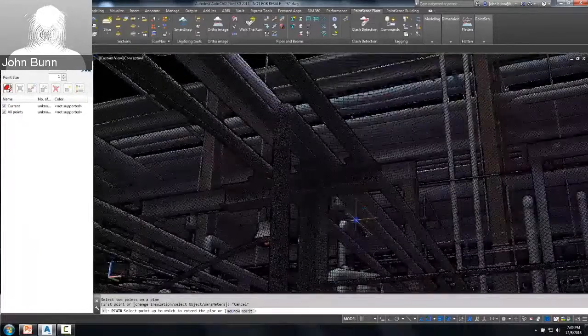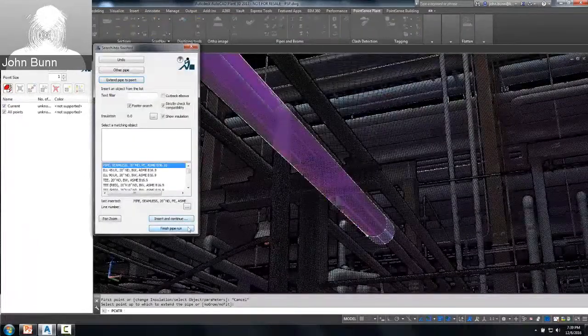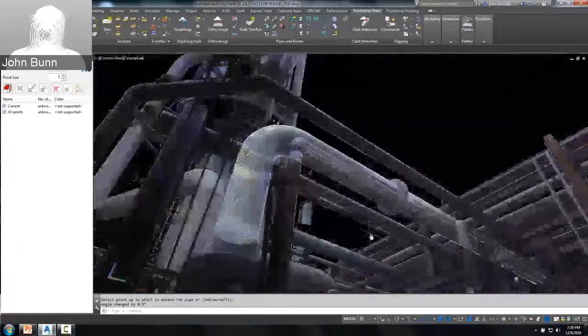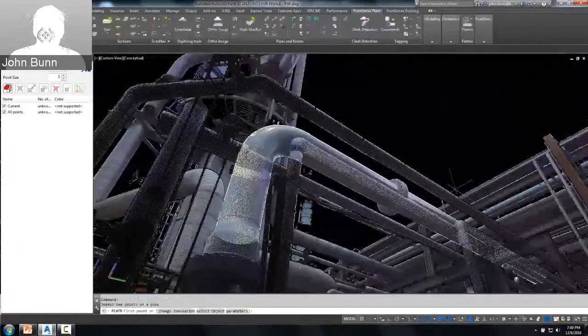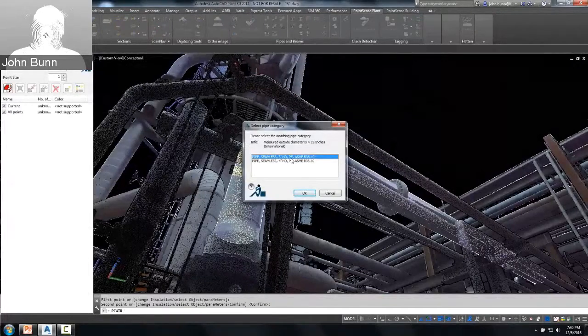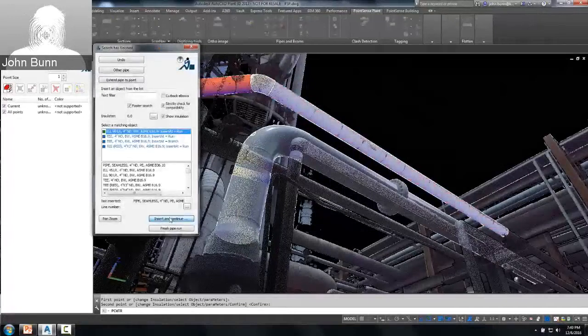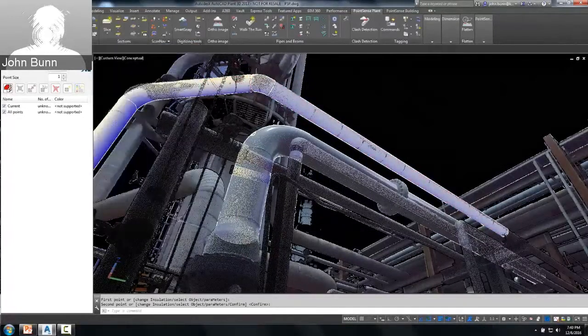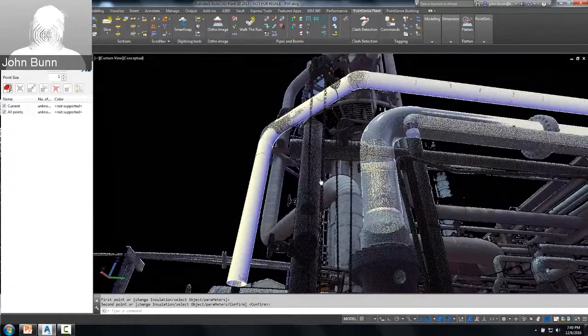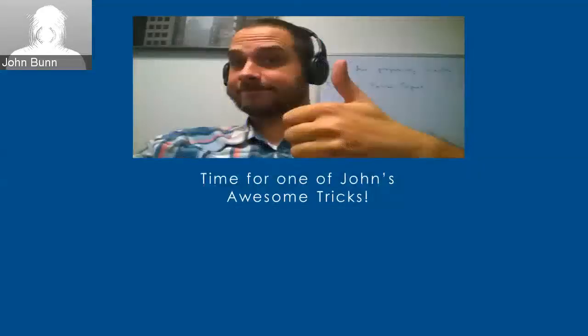On the second run, you'll actually see how quickly it finds the pipes and the elbows without the user having to pick another pipe at all, or having to wait for a search. So we'll do Walk the Run again here. Now you'll also notice the arrow pointing which way to go. That's a new feature as well. You can always just hit your enter key to accept that direction. But if you notice here, all I'm doing is hitting insert and continue, and it found the 90 and the 45 almost instantaneously. That was actually real speed there, or real time.